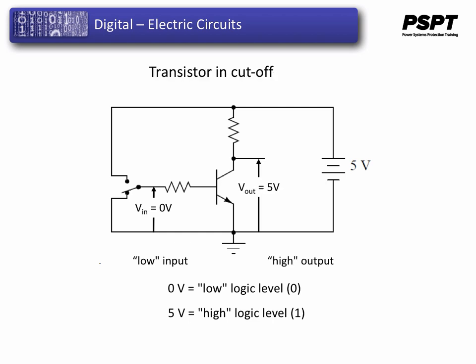Moving a switch to the other position, we apply a binary 0 to the input and receive a binary 1 at the output, putting the transistor into cutoff. What we've created here with a single transistor is a circuit generally known as a solid-state logic gate, or simply a gate. A gate is a special type of amplifier circuit designed to accept and generate voltage signals corresponding to binary 1s and 0s. As such, gates are not intended to be used for amplifying analog signals.